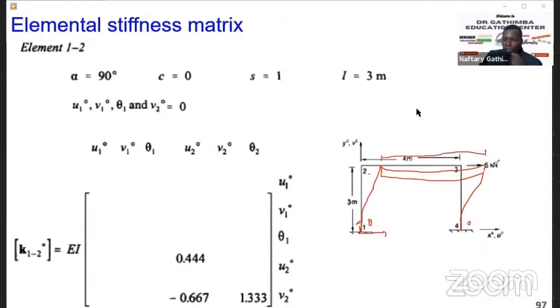the same. So if this load applied here causes a sway, and there is a deflection of amount delta here, which delta we can call U2, because it's the horizontal displacement at node 2 global for the structure, not for the member, for the structure. So the same value will be experienced here, because we are saying the element by itself does not stretch, okay, because of that axial rigidity being very high. So this deformation here, which is U3, is the same as this. So U2 is equal to U3.